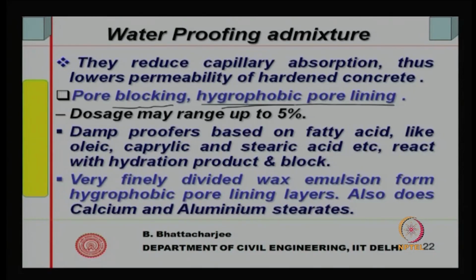When they are coated onto the capillary surface, the contact angle of water has changed. So, the ingress of water by capillary suction becomes difficult, because like mercury, which you cannot just push into any pore or capillary on its own, you have to force it.